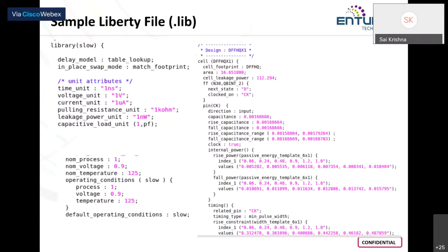The reason being, for technology nodes below 65, the channel length becomes so small that an excited charge moves in a zigzag manner, colliding with the walls of the channel and losing energy on its way. And the second thing is the temperature coefficient goes negative for those technology nodes. So that is the reason below 65 nanometer, both higher and lower temperatures will slow down your charge. So process, voltage and temperature as individual factors affect your ease of charge movement.